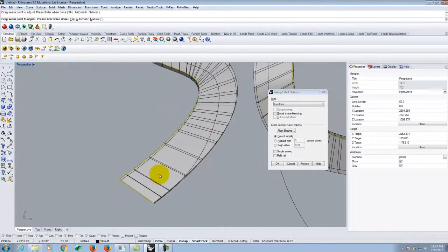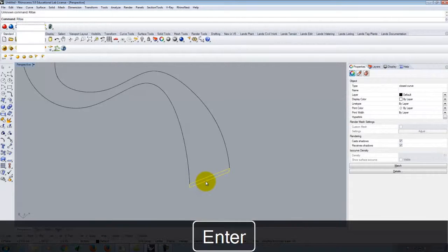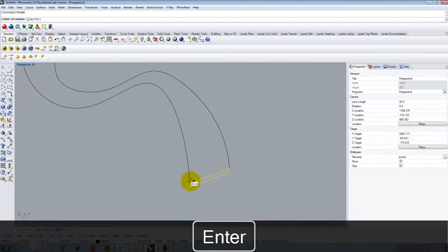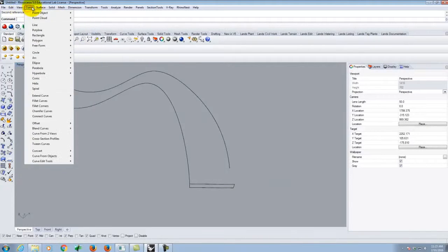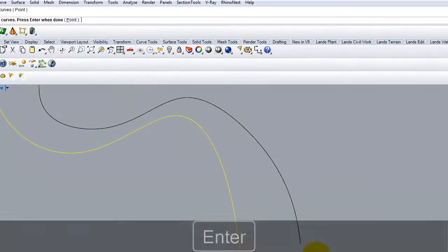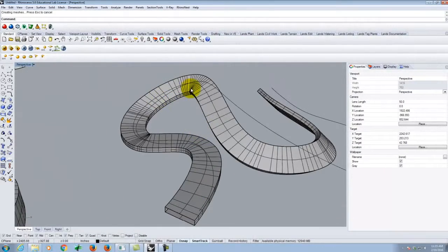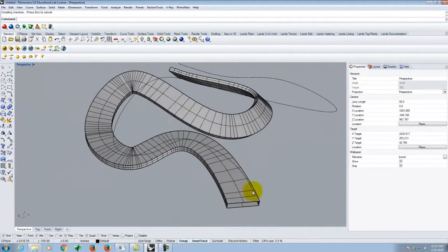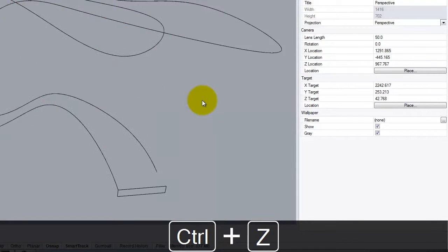Okay? So if I wanted this result to end up a little bit better, I could take this curve and rotate it so that it was a little bit more perpendicular to the start, something like that, and I get better results. So if I went to surface, sweep one rail, rail there. When I do that, I get less pinching in these corners. So how you control where this starts can make a difference. These curves are probably a little bit tight anyway for the size of what I'm trying to sweep. Okay, so let me go back to where we had here.